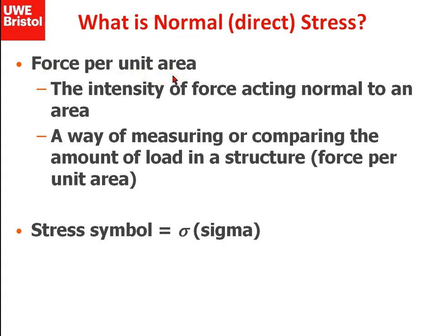So stress, whatever form it might come in, is basically a force divided by an area, and how that force is related to the area depends on the type of stress we've got. In the case of normal stress, it's the force that is normal to the area under consideration that's been pulled apart. So it's a way to measure the intensity of a force independent of its geometry, really.